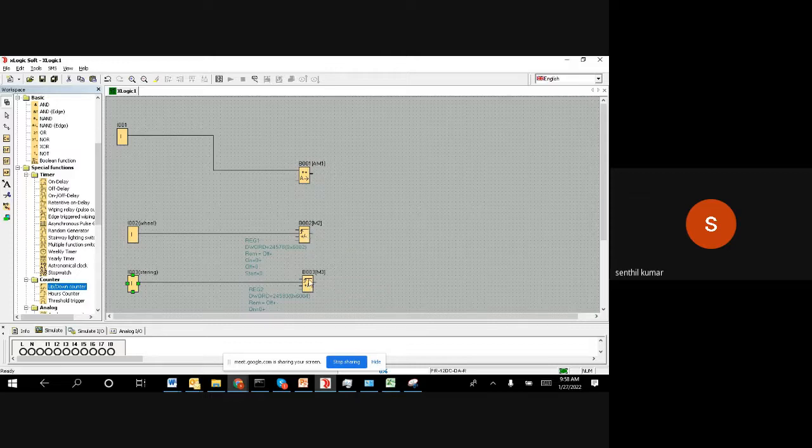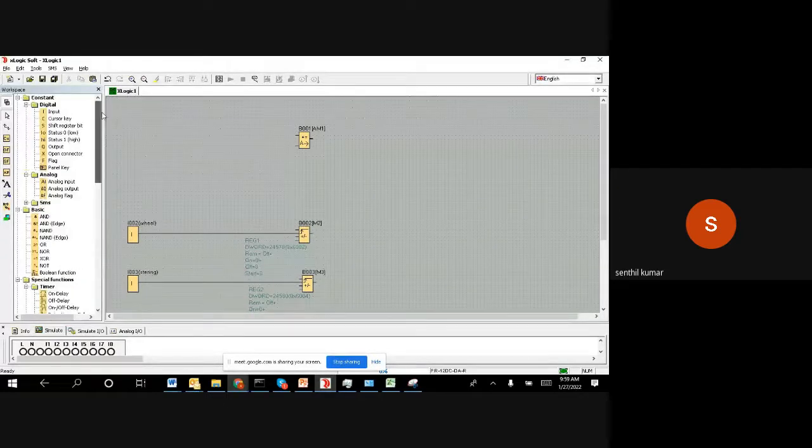So now we understand these two are going to count the production. Now we want to make an accumulator. We want to find out what the total production is. So I will set the enable always high, as we discussed, because I want to execute the task always. It's supposed to keep counting the total production.